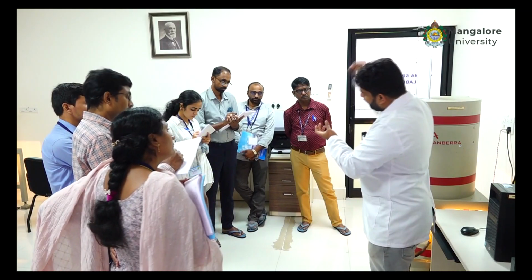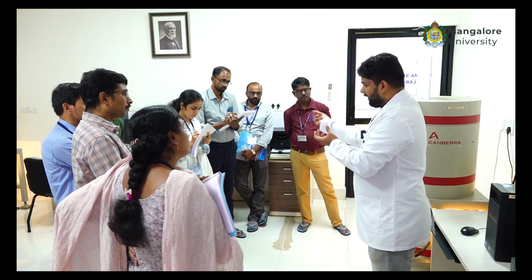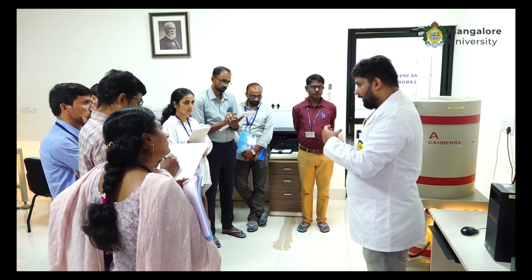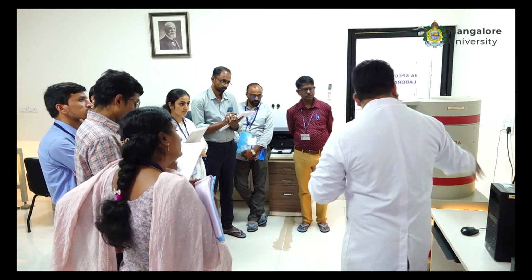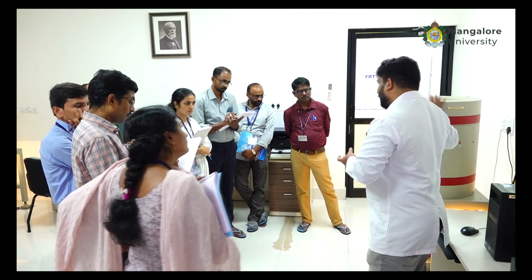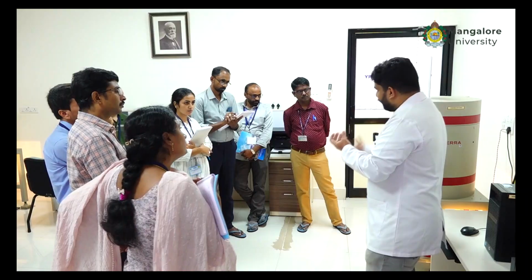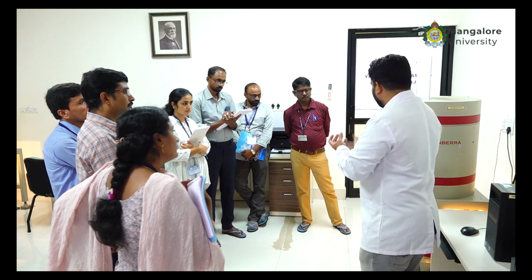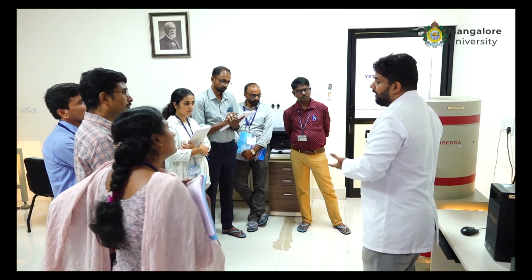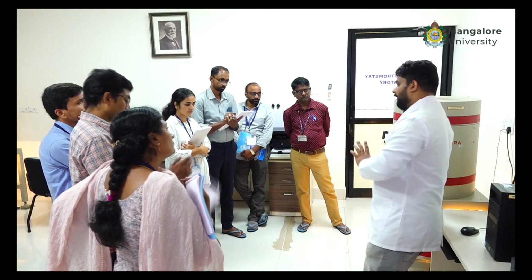When radiation falls on this depletion region, each radiation corresponds to a certain amount of current. An electron hole pair is generated and that constitutes electric current. That current is then made into this spectrum; I'll explain how. But if the detector is kept at room temperature, in addition to this count, a large number of thermal electrons are generated. That also gives electric current. I don't know how to separate these thermal electrons from the signal, so we keep it at minus 178 degrees Celsius using liquid nitrogen.